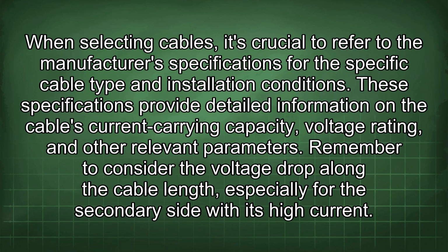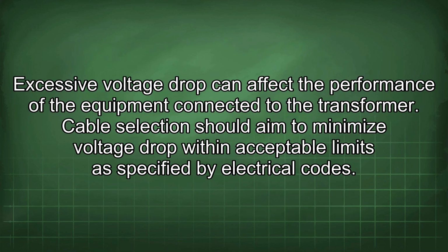Remember to consider the voltage drop along the cable length, especially for the secondary side with its high current. Excessive voltage drop can affect the performance of the equipment connected to the transformer. Cable selection should aim to minimize voltage drop within acceptable limits as specified by electrical codes.